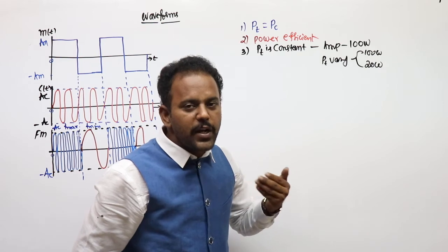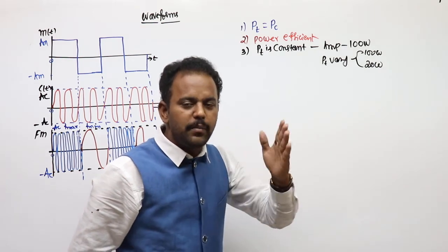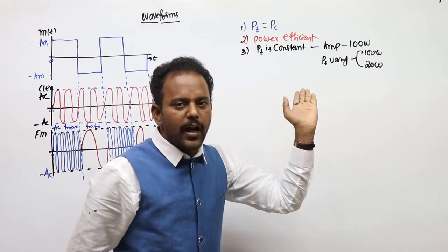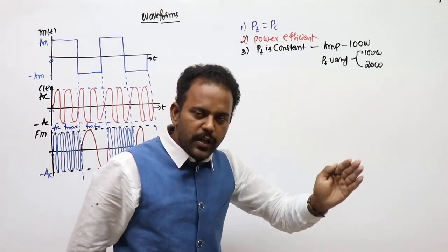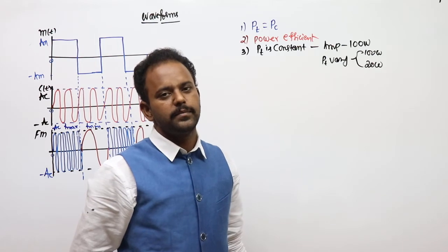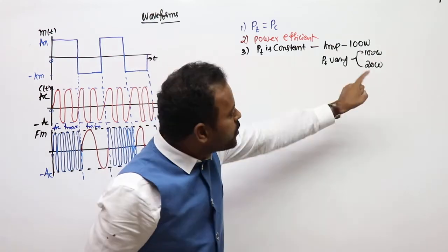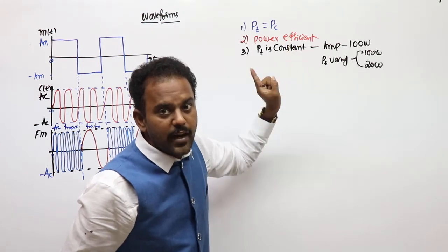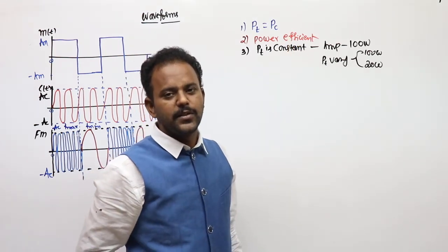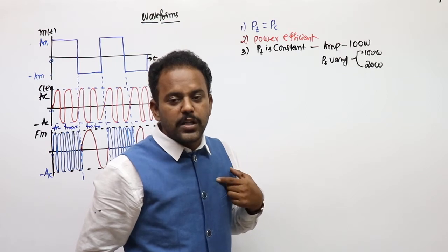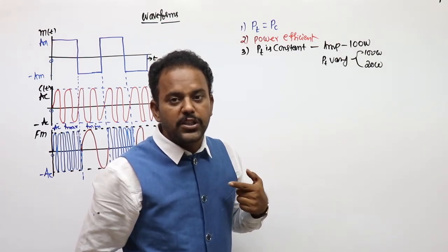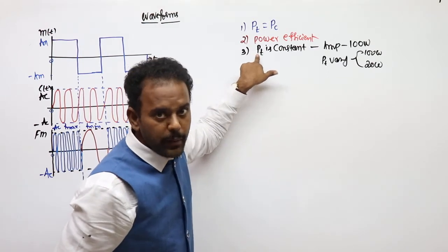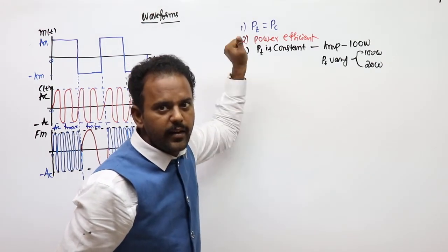For example, if you radiate our AM signal for 10 minutes, maybe in 1 minute it will have a peak value, and the rest will be less than that. You are designing your system at 100 watts, but always you are not using 100, students. So we are not using our systems at maximum efficiency level. But in FM it's possible because PT is constant.